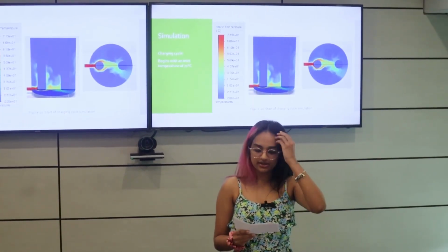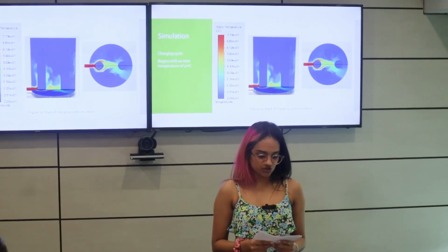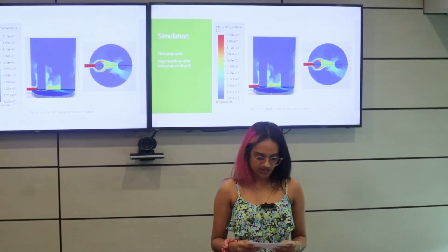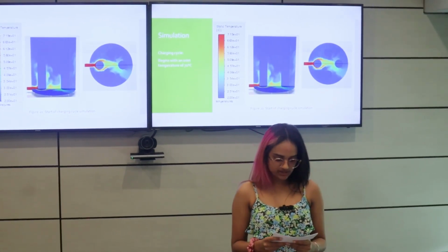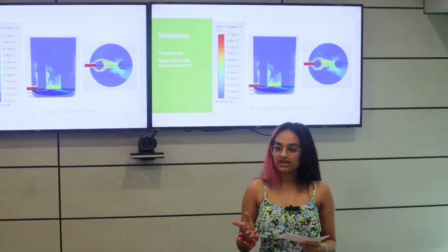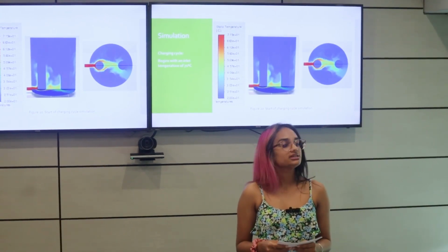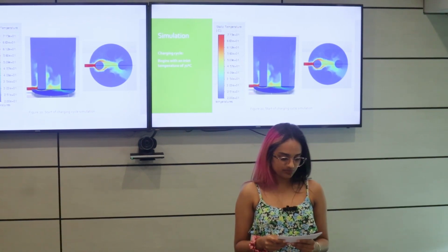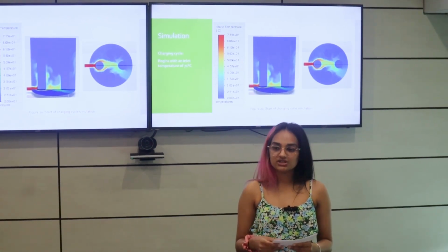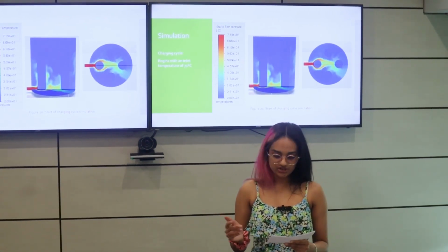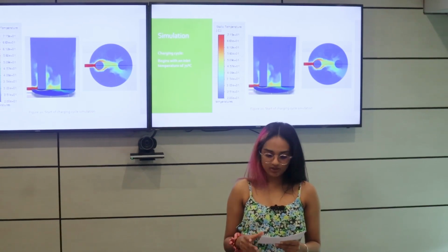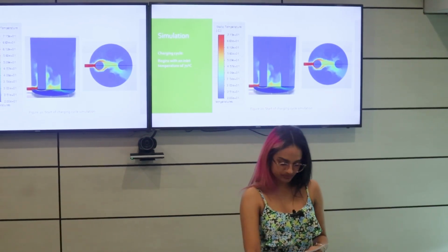The simulation was done in 2 phases, charging and discharging. First is the charging cycle, which can be seen here in figure 20. All materials begin at 20 degrees Celsius with a vessel inlet temperature of 70 degrees Celsius. This simulation is run until all of the temperatures reach 70 degrees Celsius and all of the wax has completely melted.